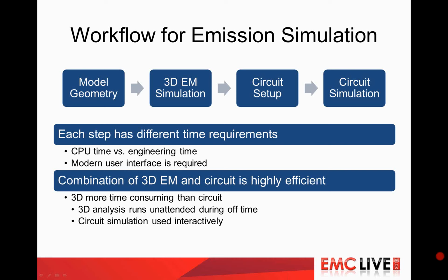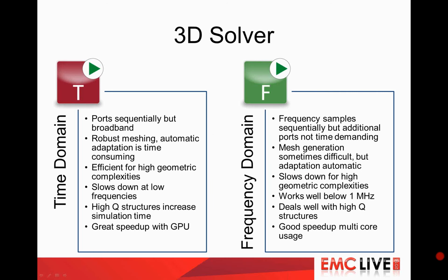And what you should not mix up here, even if it's a very simple remark, is that when I tell you that there is a time or frequency domain method, it does not mean that the results you are obtaining are only in time or in frequency domain. Because we use these solvers to analyze the geometry, and the results are afterwards calculated in a circuit simulation. And in the circuit simulation, there is the possibility to run different types of analysis. I wrote down three different types that are very typically used for EMC problems. The first and quite simple is the S-parameter task, where you calculate the S-parameters, and in terms of EMC, this is very useful.